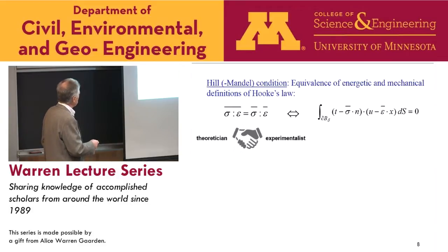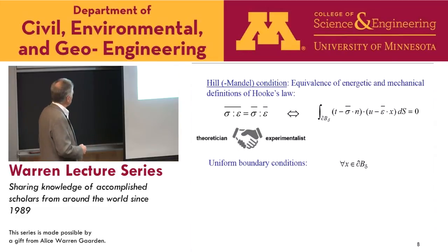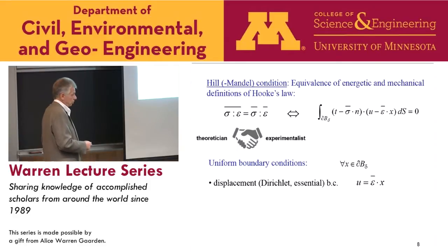which dictates three possibilities as far as loading. So three uniform boundary conditions. One is displacement, so uniform displacement boundary condition. Same thing as uniform Dirichlet or uniform essential or kinematic. So those adjectives keep on changing, and I sometimes keep on changing them as I talk.